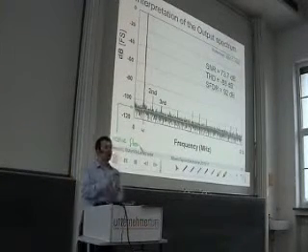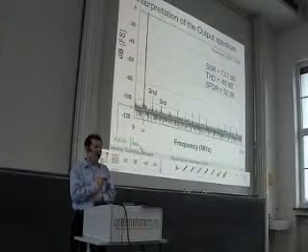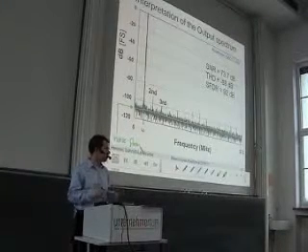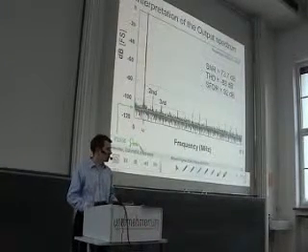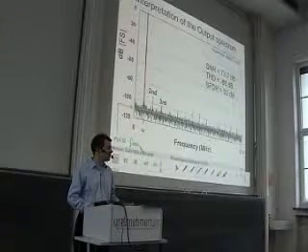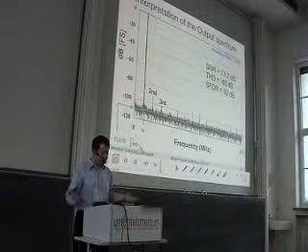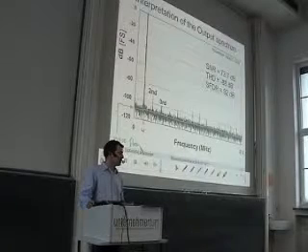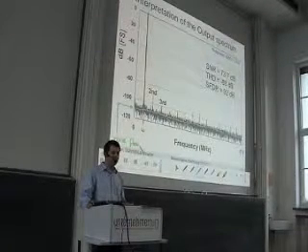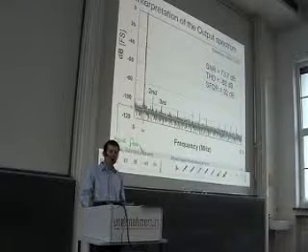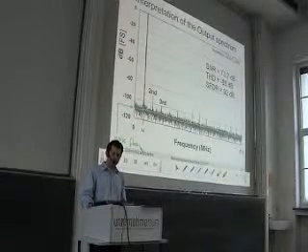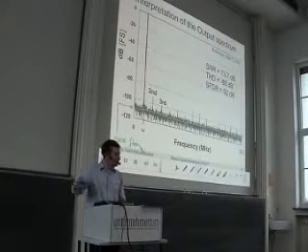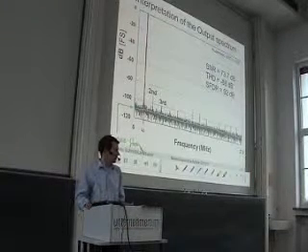In an ideal converter, there is always noise, so we get also values at other frequencies. So what is this noise from? Of course, this is the quantization noise that each ADC has. And if we assume that the input signal is random enough, then the quantization error is equally distributed. So we see this also as a spread over all frequencies. So this is a white noise. And there are also other noise sources, thermal noise, noise in the transistors, and this leads also to this noise floor. It is not always the case that it is white, but quite often.